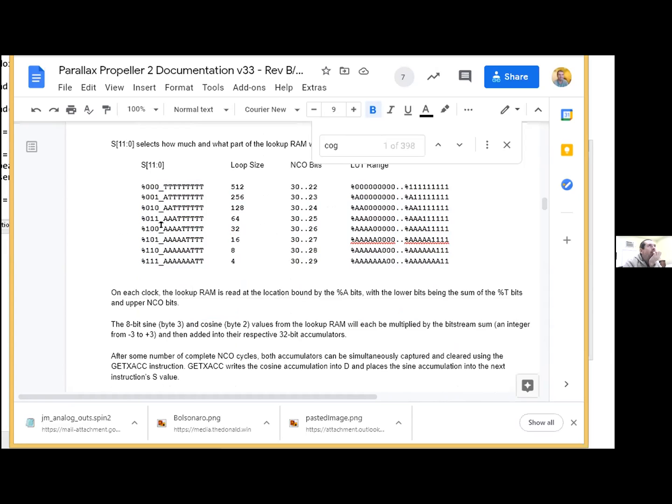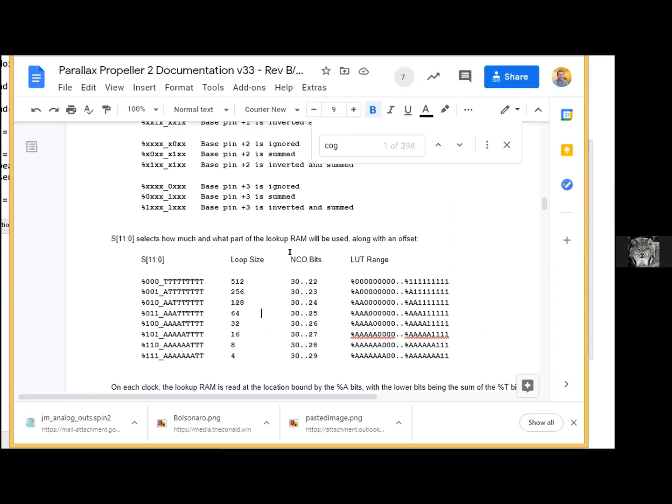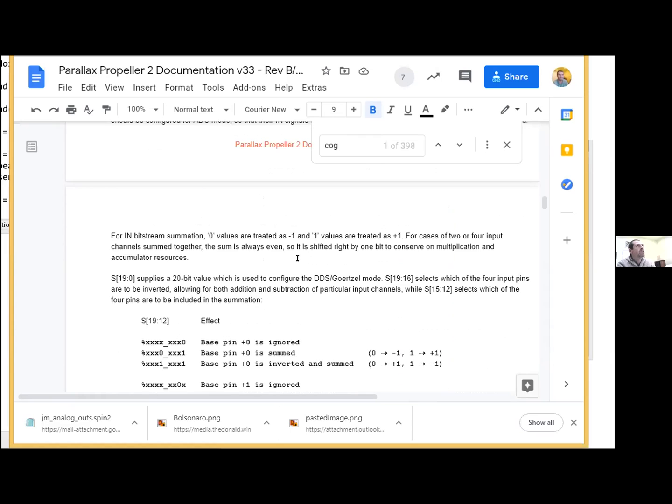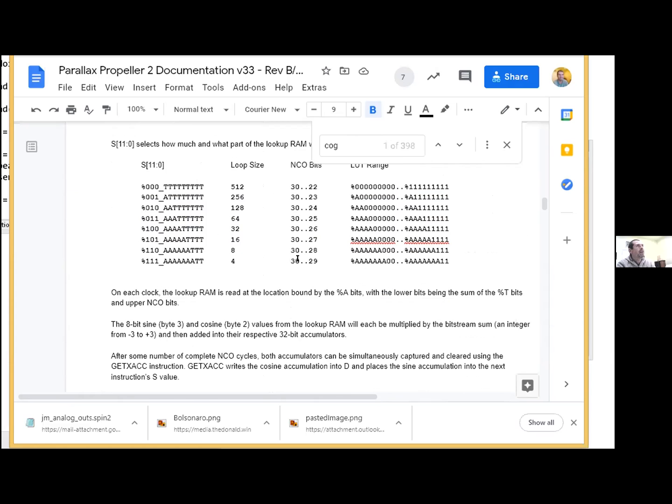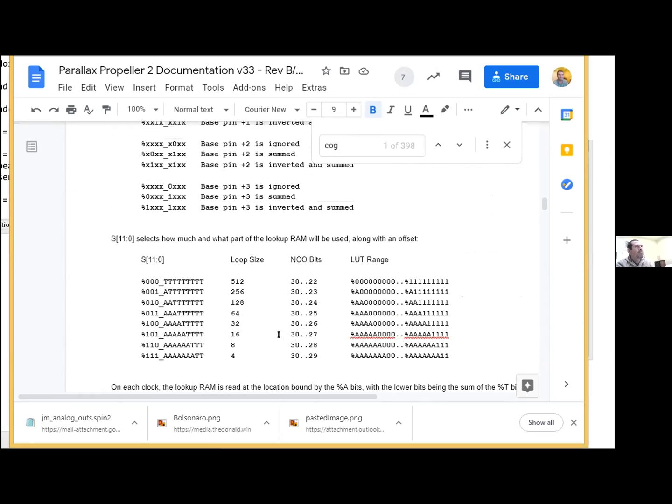With the A, we'll set which 32, which bank, and then here you can give it an offset. What's the phase offset within that bank that you want to circulate in? So the initial read point within the 32 longs. It's like saying start on the 14th long in and then loop from there. There's lots of things you can do that we designed to be able to, but we haven't even really employed any of this yet. It exists in the silicon, but it hasn't been put to any use yet.